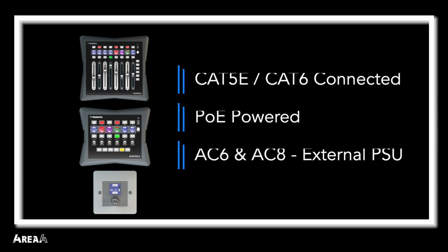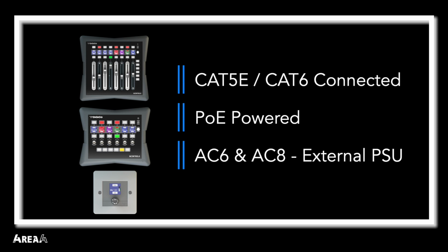All of these controllers connect to the engine via a Cat5e or Cat6 cable. When it comes to power, all of these controllers can run off Power over Ethernet, or PoE for short, which means only one cable run per controller. For added security, or if you're not using a PoE compatible switch, the A-Control 6 and A-Control 8 can also be powered by an external power supply.